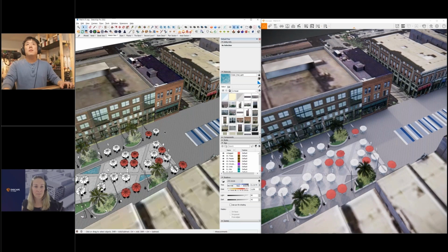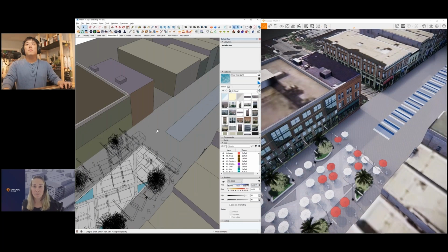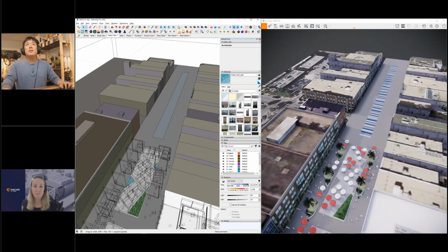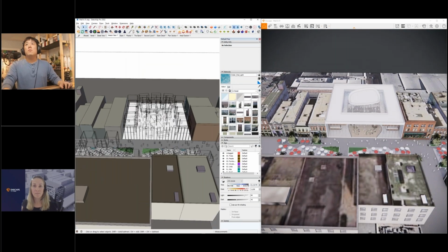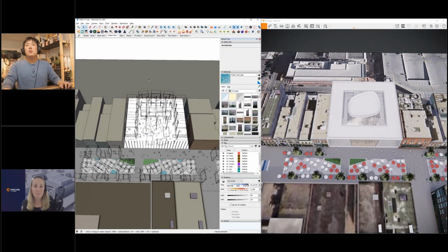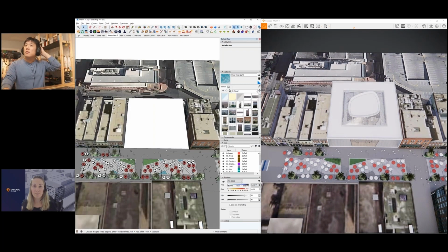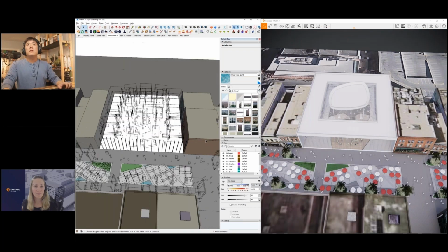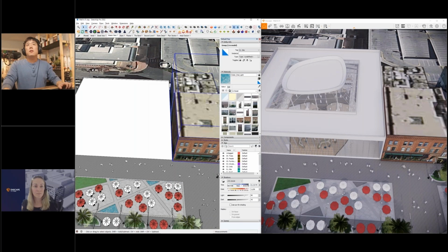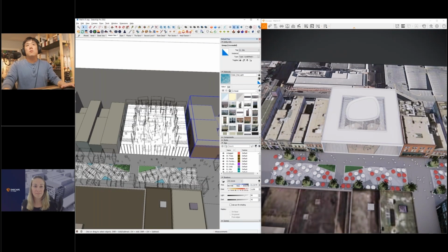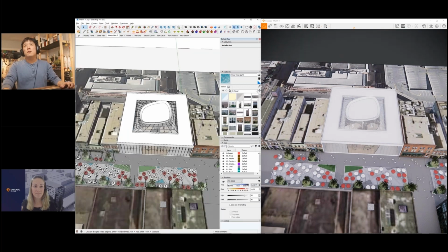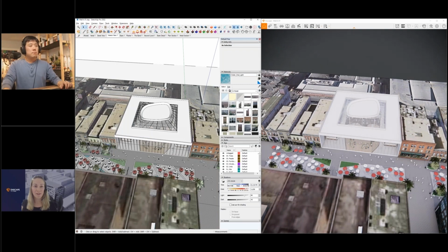So, they just kind of show up like that. Enscape does have a site context tool, but they all appear as white, and often that's not exactly the look that you're looking for. So depending on what you want, you may just take the Google image or the map data and superimpose it onto the plan and then have a couple of these buildings made for yourself. You can also rely on white blocks made inside of SketchUp or rely on Enscape's site context tool as well. Brilliant, thank you.